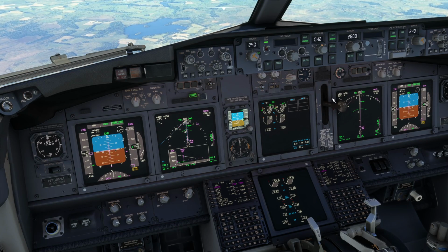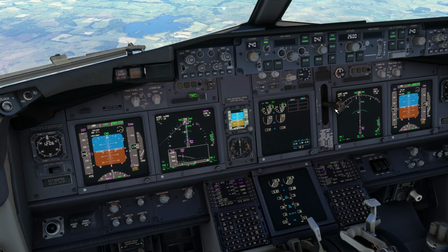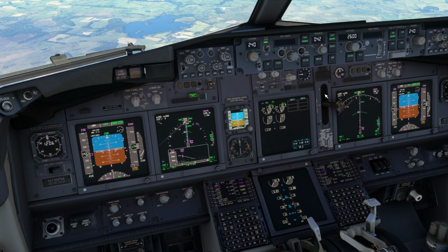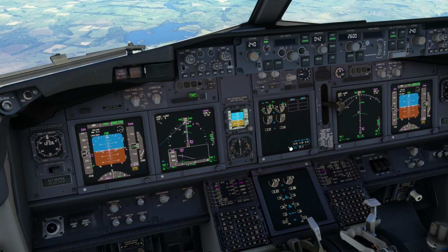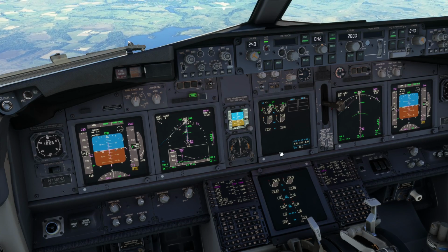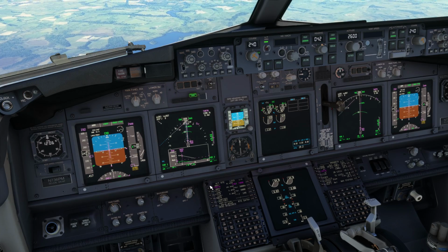Oh, something else we missed along the way. We shouldn't have had the landing gear lever up all the flight. We should have put it into the off position as soon as the landing gear was up. Otherwise you're charging the hydraulics for the landing gear the entire time.